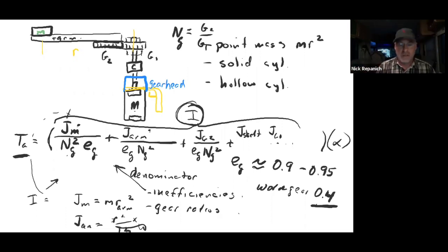ratio, which really, if you think about this, and you're really trying to make this out here turn 1 rev per second, and this motor turns 30, you're looking at a 30-to-1 gear ratio somehow. Are you going to have a 30-to-1 gear ratio between these two gears? That means this gear has to be 30 times bigger than that one. Okay, that's not realistic. And so gearing, for the most part, no, we don't do that.